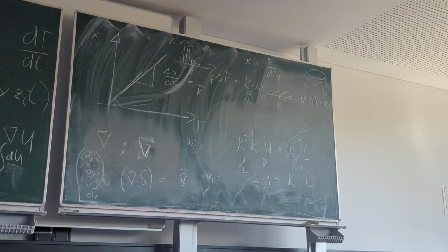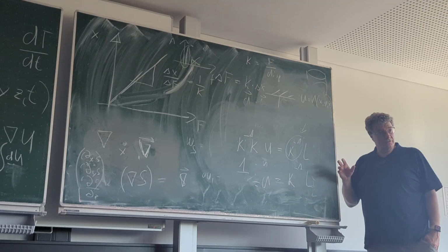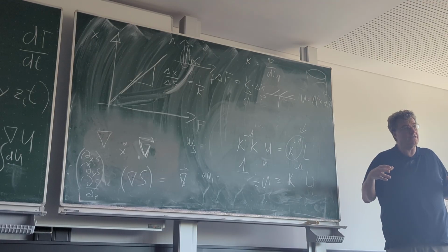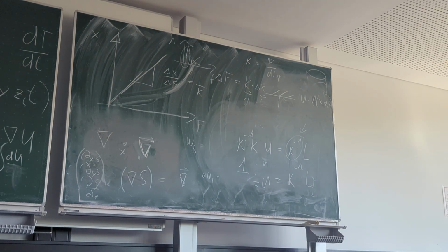You may already guess, if you don't use the direct method, you go to some iteration. Iteration means it has to go step by step toward the solution. That can go wrong. If you draw a 3D geometry and model in 3D, then it automatically goes to some kind of iterative solution. That is another reason why the strong recommendation is to start the modeling with 2D. Then you don't have a convergence problem, it just goes straight.